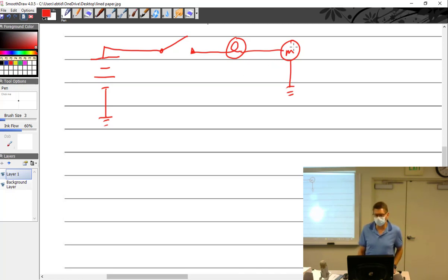So let's say this motor is a very critical piece of equipment and it runs the landing gear motor. And that's how I get my landing gear down. So I really want to know when that motor's running, all right? It's very important to me. So I've designed this circuit. And so, all right, I'm coming in for a final. Coming in to land. I don't want to land on the belly, so I energize this switch. Current flows through here, lights up the light for just about half of a second, and then, whoops, it just burns out that light.